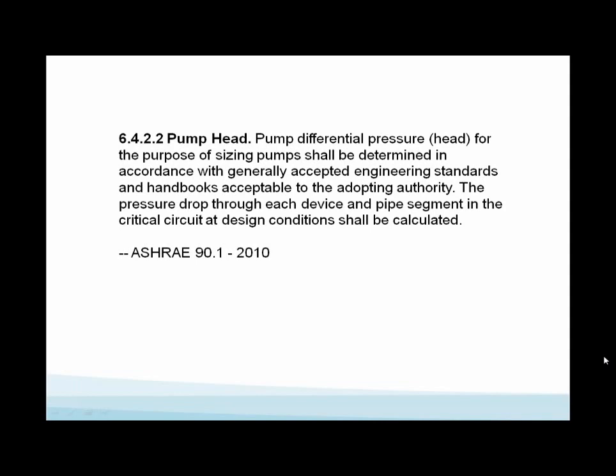You can read in detail right quick, but it basically says you have to do a detailed pump head loss calculation with all the fittings, all the devices for the critical circuit, for the critical path. You've got to do that calculation, and you got to put it in the file. Yes, ladies and gentlemen, we have to do a pump head loss calculation in detail and put it in your job file. We've never been told that before.